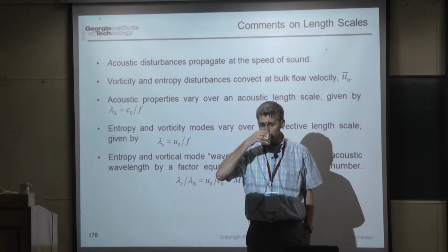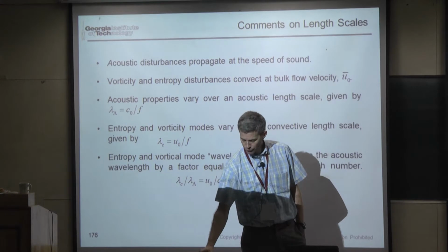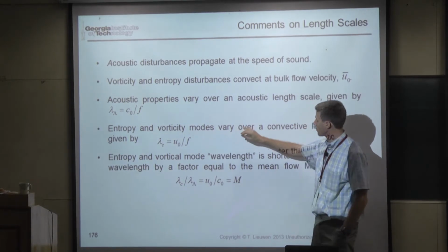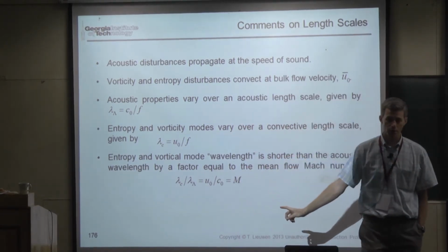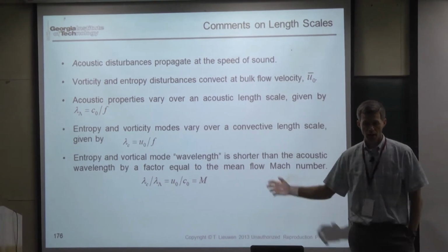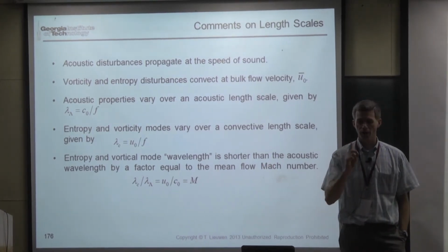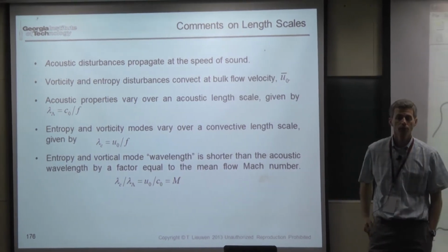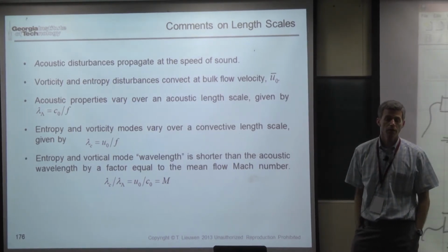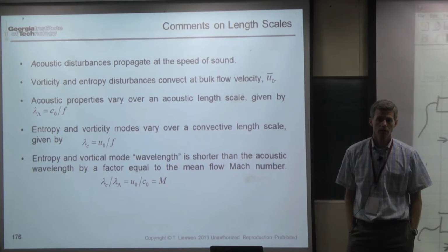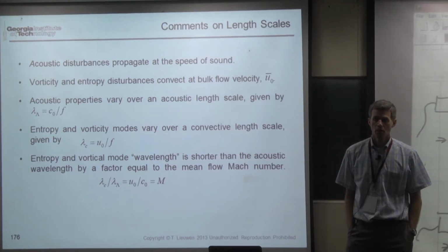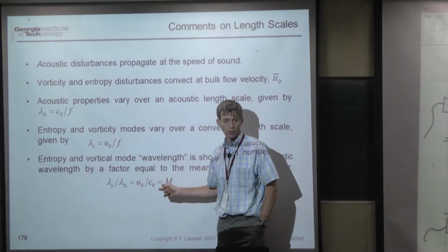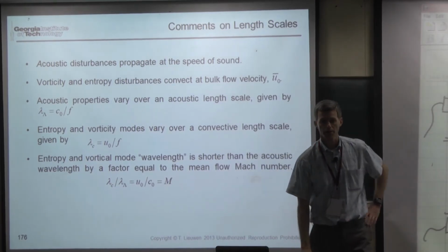Convective velocities are less compared to the mean flow velocities. When we say the convective velocity, it is the mean flow velocity for this problem. Since there's no spatial gradients, everything's moving at the mean flow, at one value. There's only one velocity scale, U0. So do the scales also approach each other at non-sonic conditions, like a subsonic condition? In the low Mach number limit, do the length scales and time scales approach each other? What are the conditions for them to approach each other? So they won't. That's the key point here: those length scales in a low Mach number flow are going to have an order Mach number variation between them.